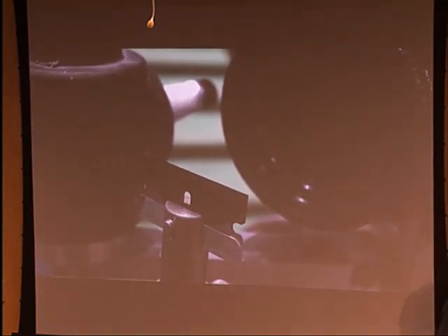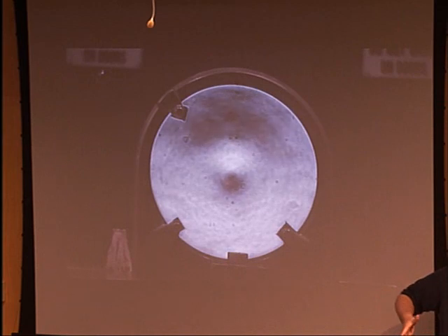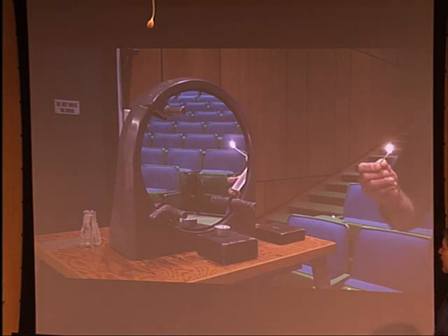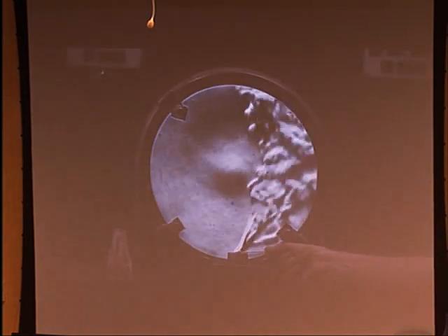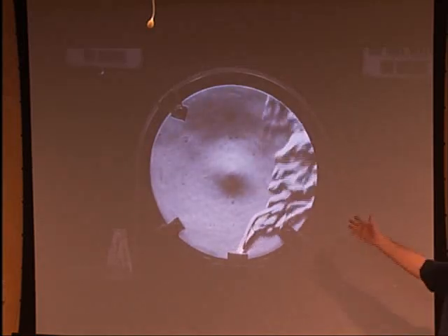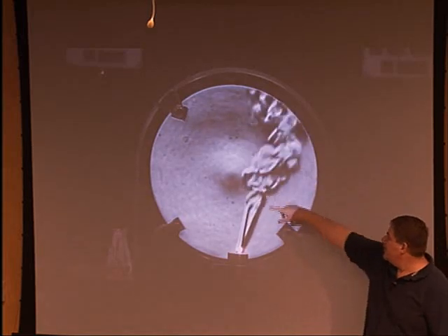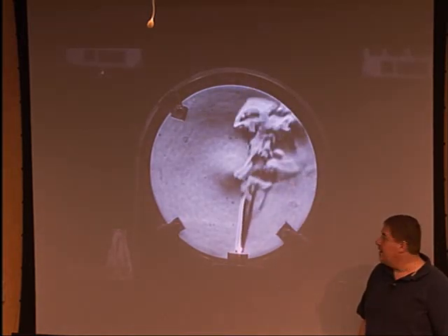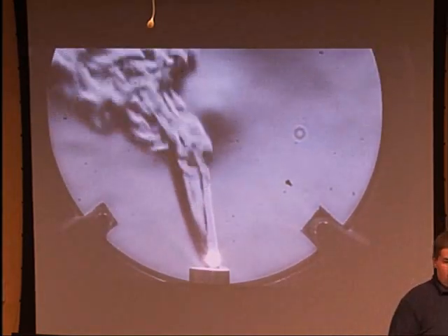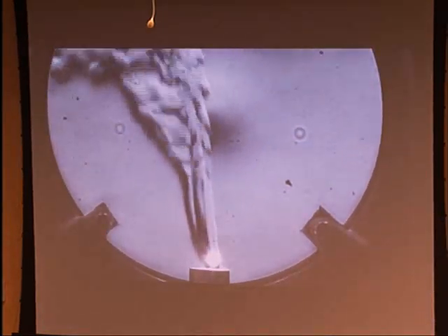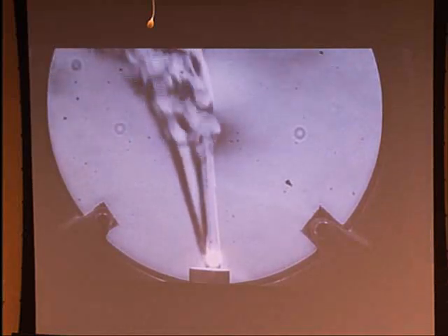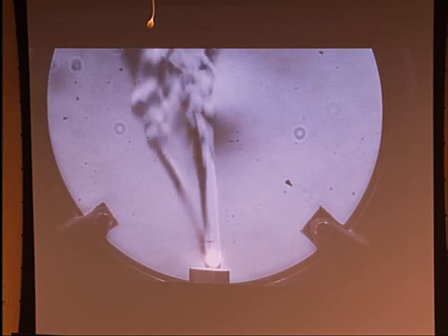Schlieren, like I said, is a technique for being able to see the invisible. So this is a razor blade and a camera lens, and next to it is a source. And then across the room is this big mirror. And so you can put things in front of this mirror and actually see distortions, in this case in the atmosphere here. So the heat from the candle flame here is changing the index of refraction of the air around it. And the setup is changing the phase information that's usually invisible to us into contrast so that we can perceive it.